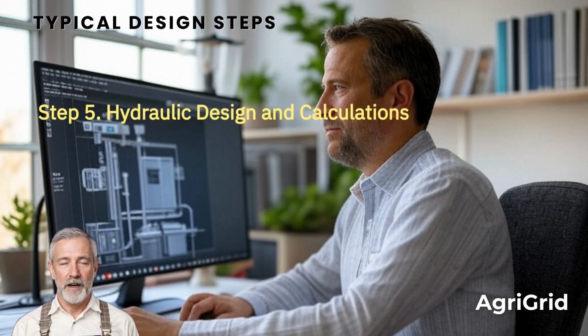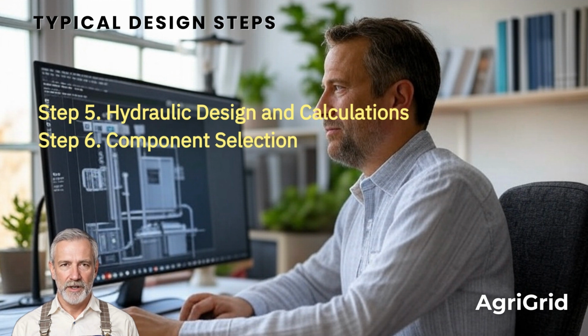Step 6. Component selection. Next, you will choose the right equipment for durability and performance by selecting pipes, e.g., PVC, polyethylene, fittings, and connectors. Pick delivery devices such as sprinklers, drip emitters, based on coverage and water distribution needs. Choose valves, filters, and pressure regulators to protect and control the system. Opt for a controller or timer, manual or smart, for scheduling.